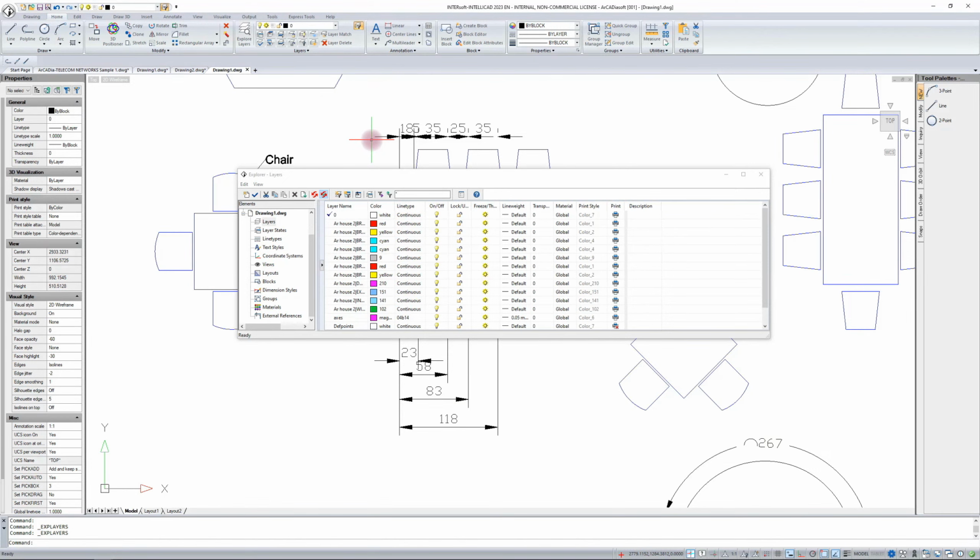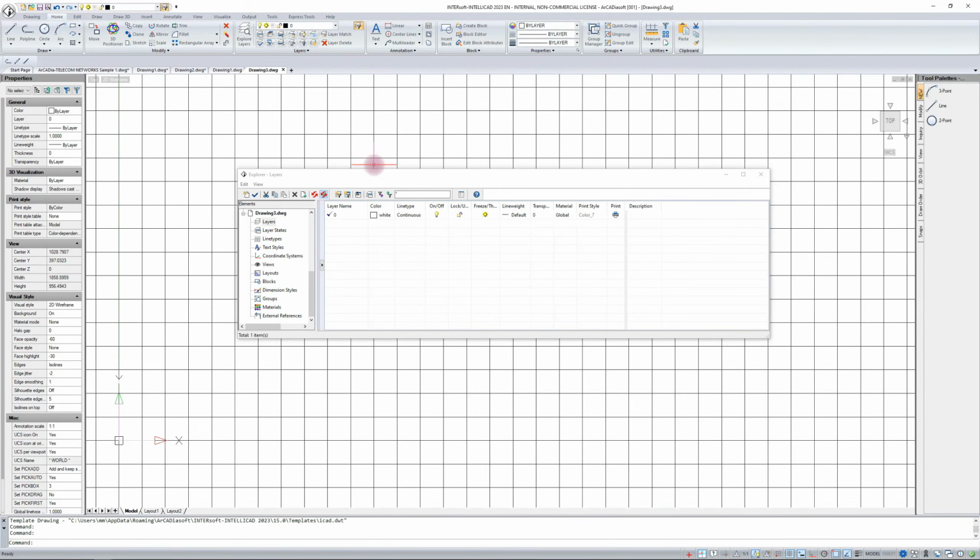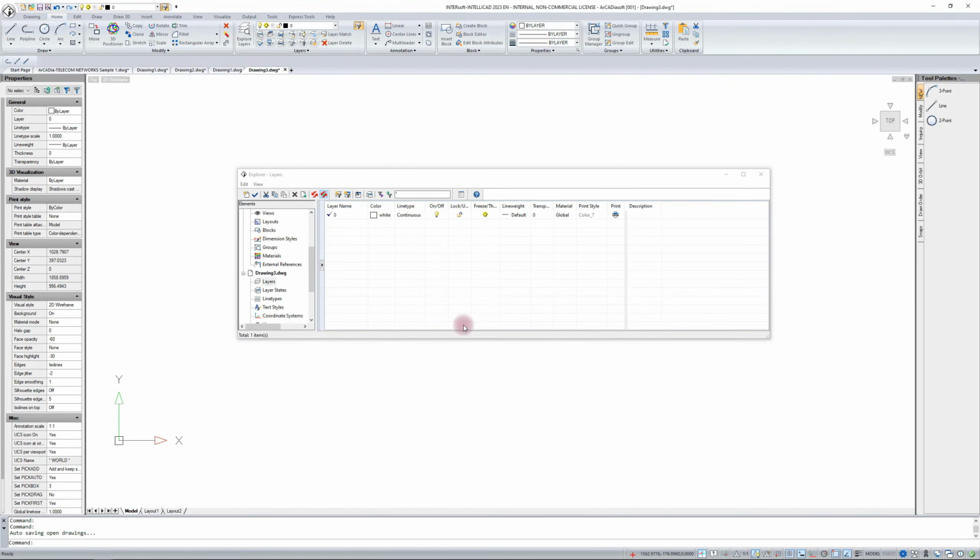Okay, the drawing we must have is a blank drawing. That is, we open a new one. Whether it will be with a grid or without, it will depend on us. I will turn it off, because on the white background, the grid bothers me. We can add layers for ourselves. Remember that the drawing is to be blank. Only the settings are defined. That is, no lines, no blocks, no text. We don't do anything like that. It is just supposed to be an empty document. Blank, and we can start drawing anywhere, and nothing will go wrong for us later when we work on it.